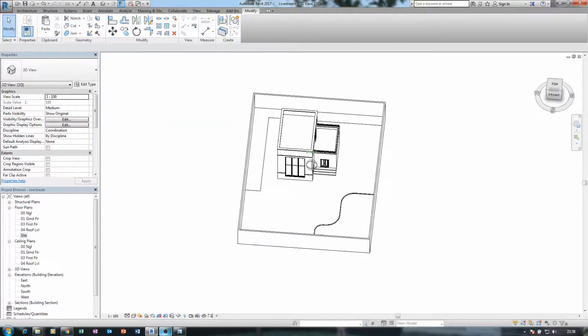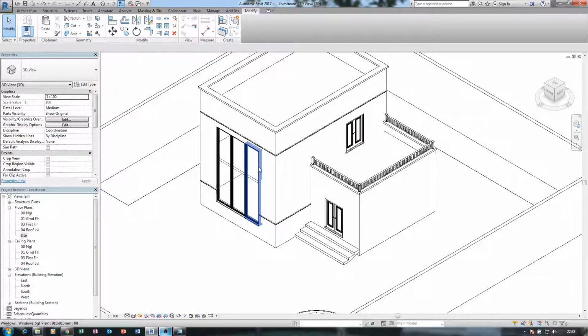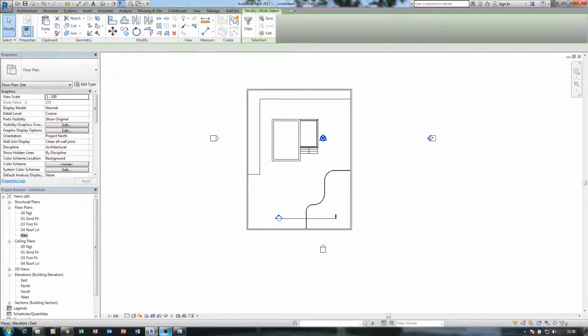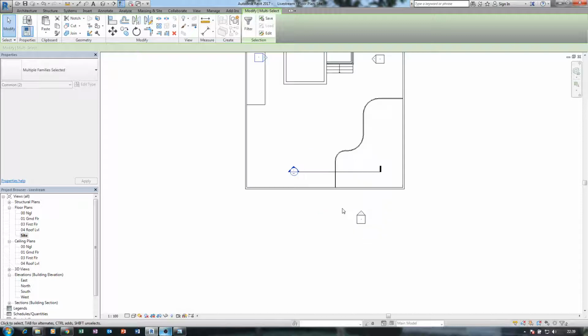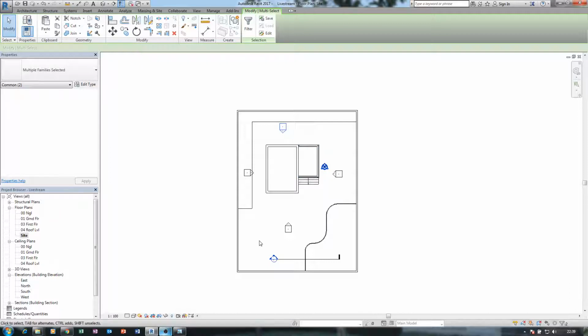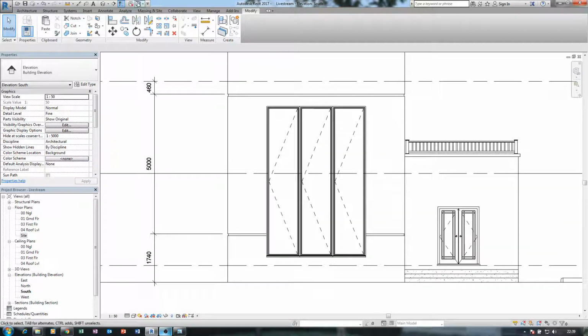As you know, I always try to apply my materials in Revit before I now move to 3D Max. So what I'm going to do now is move this inside, move this inside, move this inside, move this inside. But always be careful when you are picking these things, because they represent your views and elevation. So I'm coming here, and this is what I have. What I want to do now is to use split and split this face.